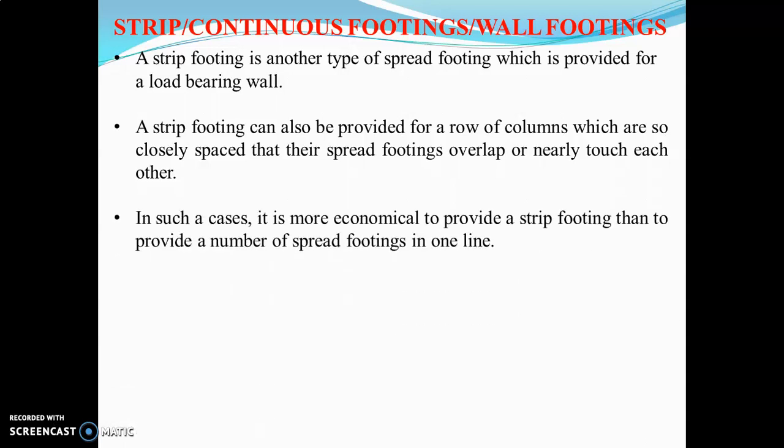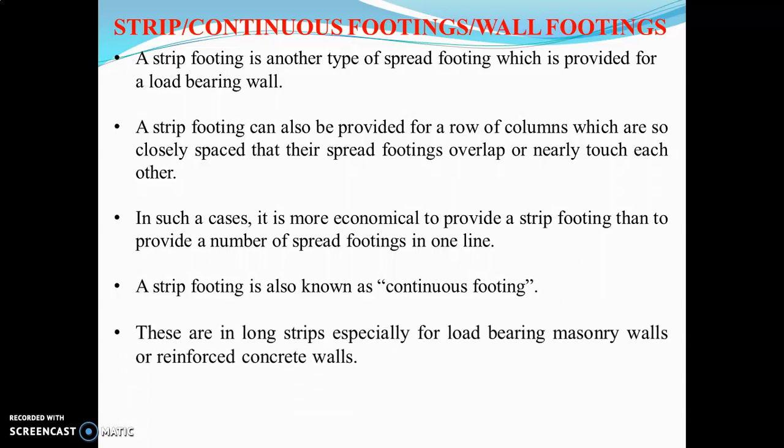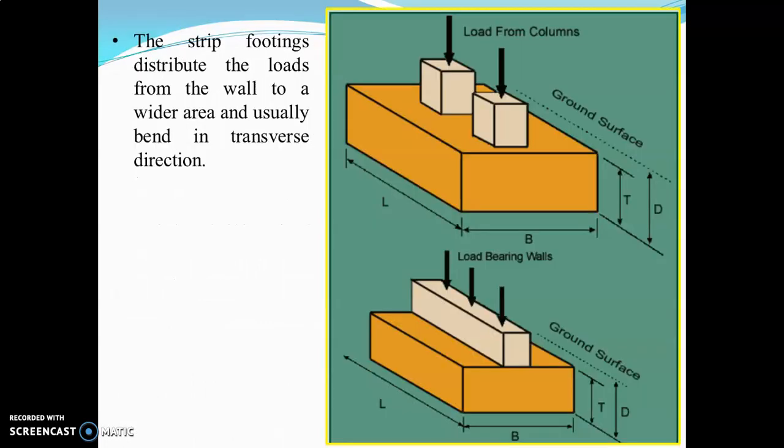In such cases, it is more economical to provide a strip footing than to provide a number of spread footings in one line. A strip footing is also known as continuous footing. These are in long strips, especially for load-bearing masonry walls or reinforced concrete walls. However, for load-bearing masonry walls, it is common to have stepped masonry foundations.